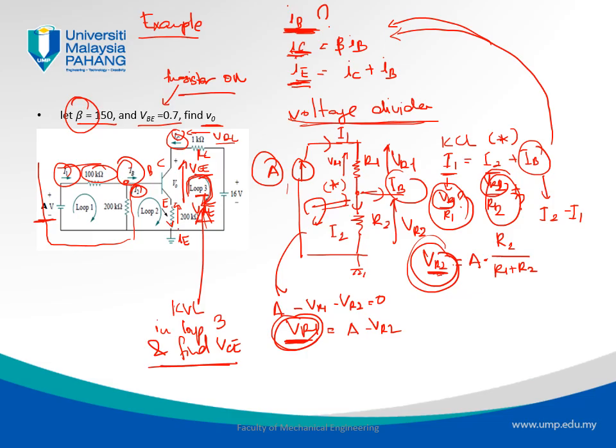So that's basically what we do in transistors. Just use the same properties, and then just play around and try to figure out how to find IB, because this is basically the most important parameter. It is the current that actuates or switches on the transistor, and if you find IB, then the rest you will find, right? So that's all about the exercise, and now we will look at another example of a transistor configuration that might be interesting to use.